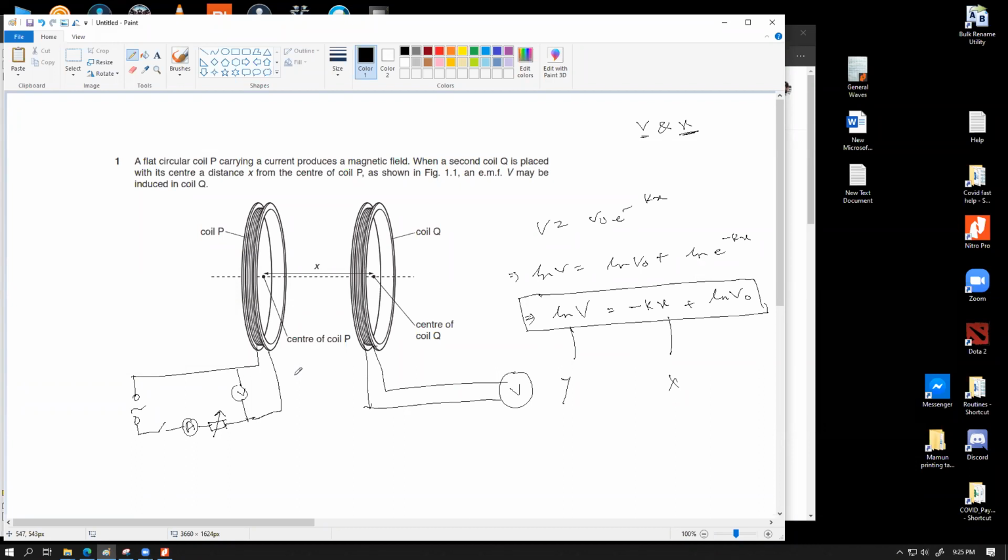Whenever you connect a voltmeter with an AC supply, the voltmeter typically always gives you the RMS value. For example, the multimeters that you have used in your laboratory. In that, there was a certain segment of the radial display where it showed the AC voltage. Typical multimeters that we have access to in laboratories always measure the RMS voltage of an AC supply, irrespective. If you want to measure the maximum voltage, then you need to multiply that by root 2.